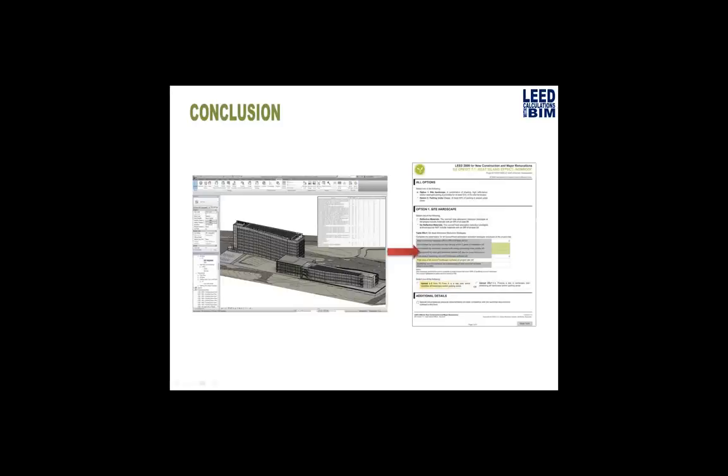So really, you can see that this is a process, right? To recap, in Revit you'll have your template files, and you'll create your parameters, your schedules, your families, all that custom content that you need in order to make this a repeatable process. In some cases, you can take information directly from Revit and push it up to the online system, but you still have to print this out to a PDF or something, go to the LEED online system and manually upload it. So there's still a bit of a disconnect.